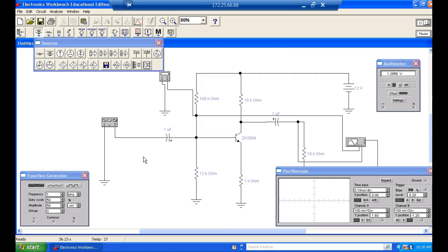Well, if you drive your power amp on the output of your radio, then you're going low impedance into low impedance, right? If you drive it on your preamp side, and a lot of radios give you a split, they'll have a jumper on the back where you can unjump it and disconnect the power amp on your radio and bring your power amp into that.